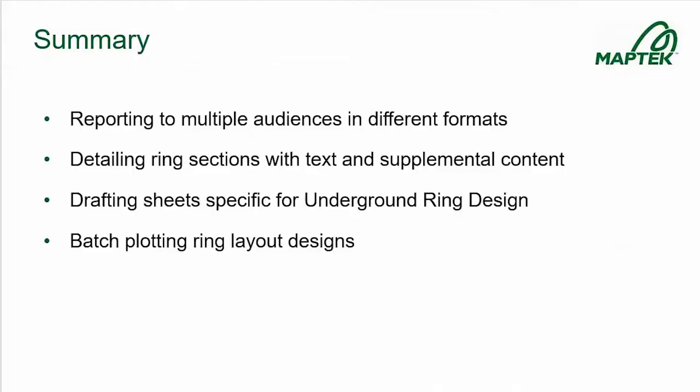All right, so in summary, we went through reporting to multiple audiences in different formats, from very simple reports to in-depth detailed reports. We looked at how to detail your ring sections with text and supplemental content such as dimensions or section profiles of triangulations. We looked at what makes an underground drill and blast drafting sheet unique and how it can be used in the underground ring design menu. And then we also looked at batch plotting of multiple rings, an entire ring set. Do we have any questions?